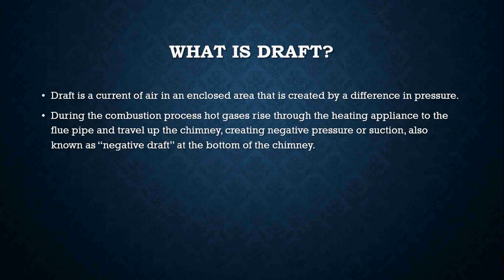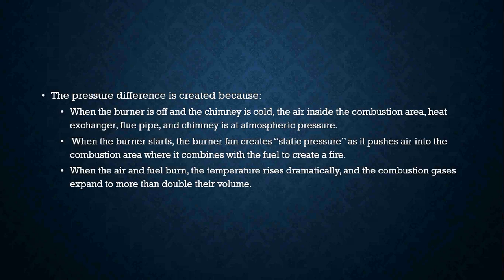So draft, what is it? Draft is a current of air in an enclosed area that is created by a difference in pressure. Okay, during the combustion process, your hot gases rise through the heating appliance to the flue pipe and then out the chimney. When that happens, it's creating a negative pressure, or what we like to think of as suction, also known as negative draft, at the bottom of the chimney.